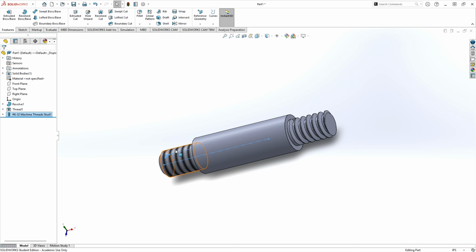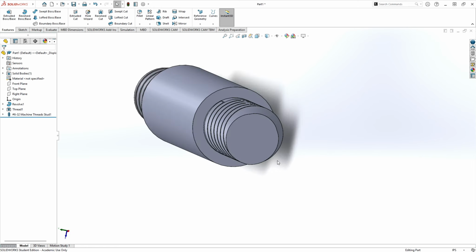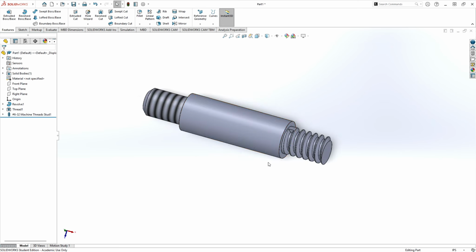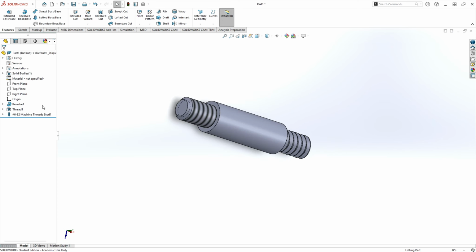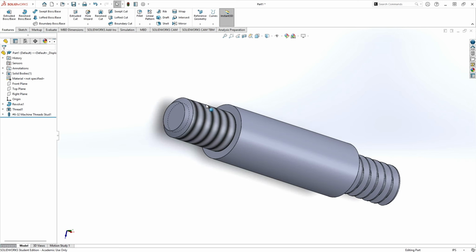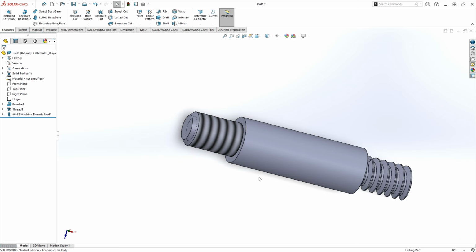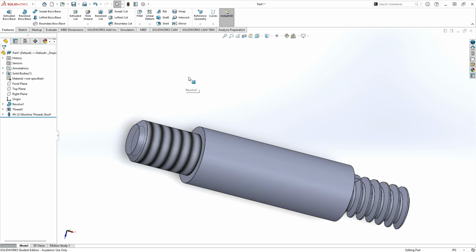One advantage of this is it uses a lot less processing power. If you think about the math that's involved with making these helixes, if you have an assembly that has lots of threaded features in it, thousands of fasteners and stuff, it can bog down your large assembly. So you generally try to avoid doing these kinds of threads unless you need them for illustration purposes, and go with the machine thread studs. Okay, it saves lots of memory, file size, that kind of thing.